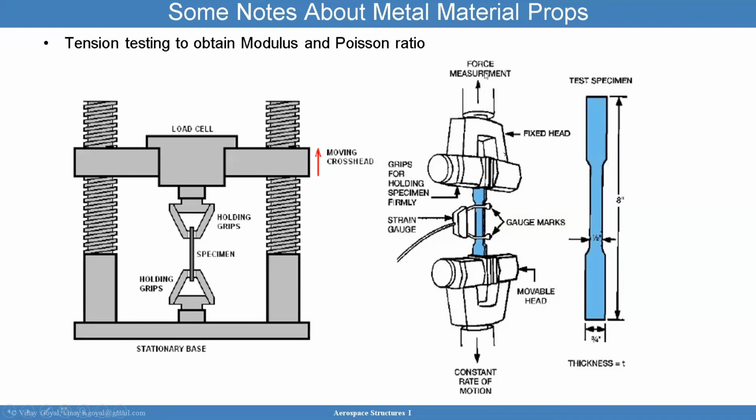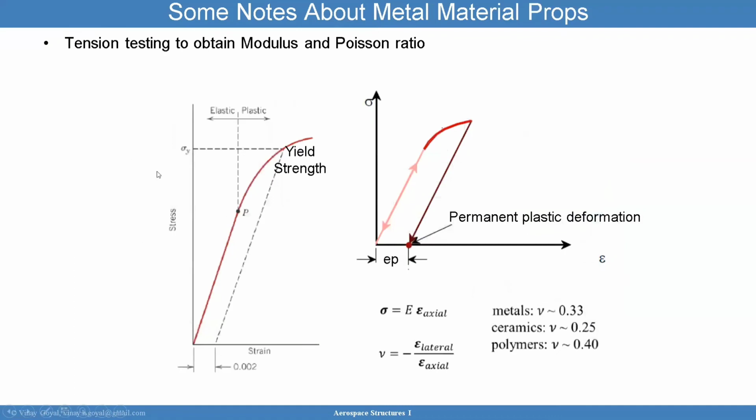What you do is you take the force measurement divided by the cross-sectional area, and then you know the strain as a direct measurement. So that gives you stress versus strain. And then the curve will typically look like this. And then at a 0.2% offset on the strain, you draw a parallel line to this here, and that marks your yield strength. And that's useful because if you didn't have the 0.2%, it would be kind of arbitrary to know where the yield strength is really occurring.